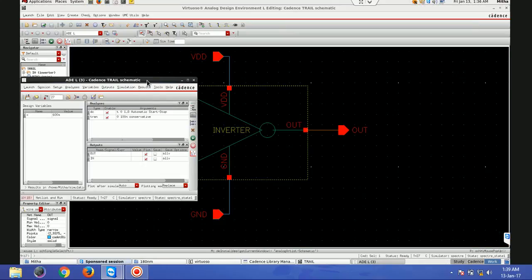So in this tutorial, what I did, I removed all the sources which I used earlier, VDC, VDD, etc., and ground. Then I used pins, and this is the same process. When we have to go for layout, we have to remove all those things and replace them with pins. Then we'll go for layout.